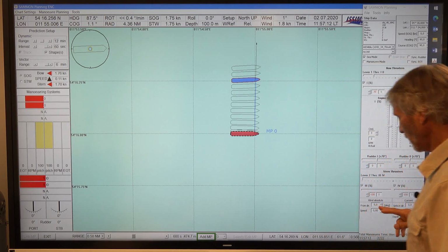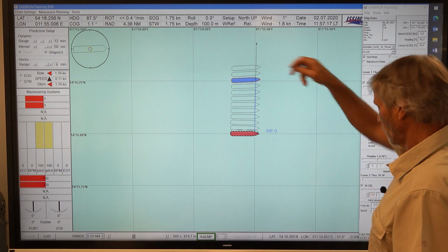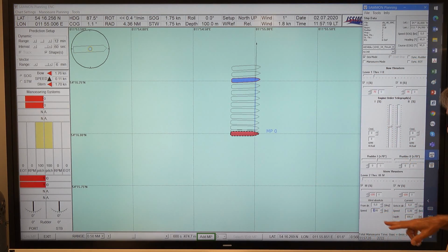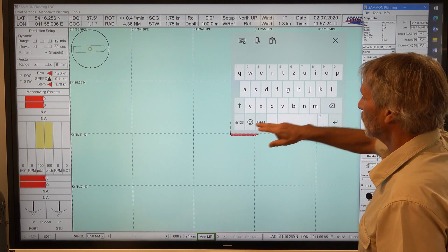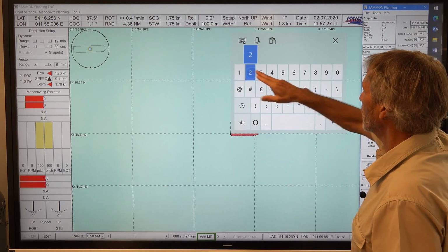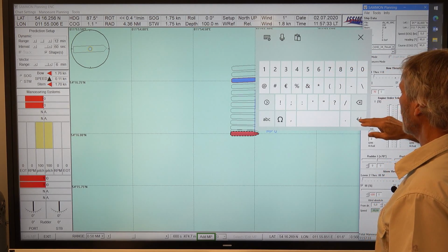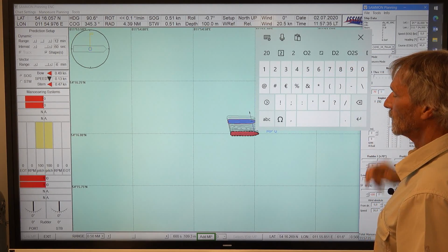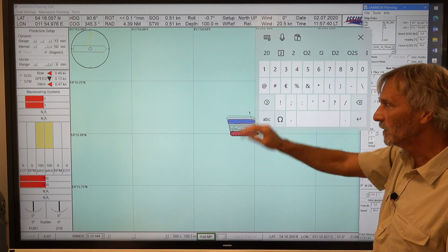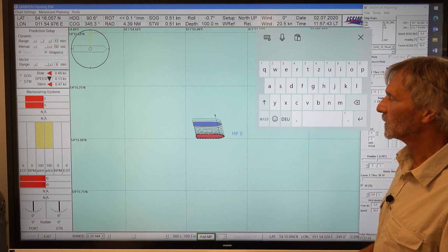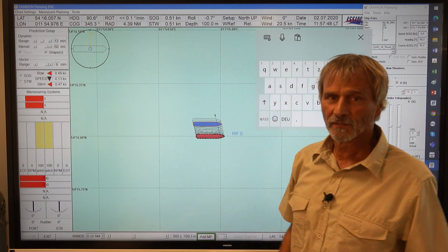Then we have to set here down there the wind direction. We will have the wind from north, so 0 degrees, and we will set the wind speed to, let's say, 20 knots. And we will see whether or not the ship is able to stand this one. So 20 knots of wind. So we see, okay, the shapes are squeezed together, but the ship is really able to move against the wind with a drift speed of half a knot.